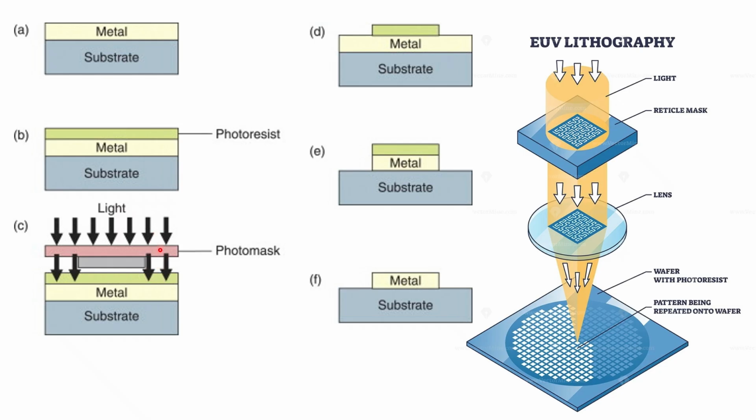So in the regions that are exposed by light, for example, the material is weaker, and in the developing solution, it can be removed. So this allows the transfer of patterns on a mask to patterns in photoresist. The photoresist is then used in turn as a mask to etch the metal. After the metal is etched, you can remove the photoresist, and this is how one transfers the pattern from the mask or design to the substrate.